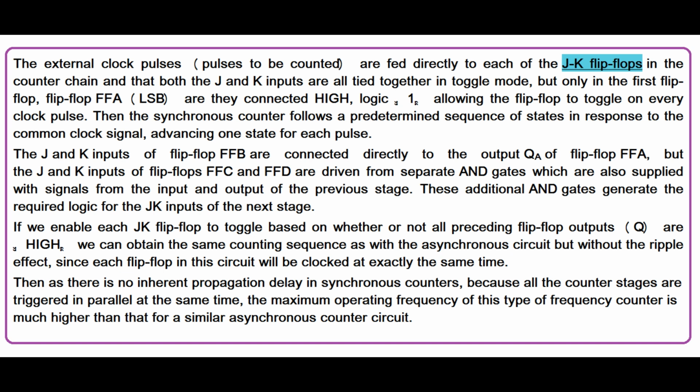Then, as there is no inherent propagation delay in synchronous counters, because all the counter stages are triggered in parallel at the same time, the maximum operating frequency of this type of frequency counter is much higher than that for a similar asynchronous counter circuit.